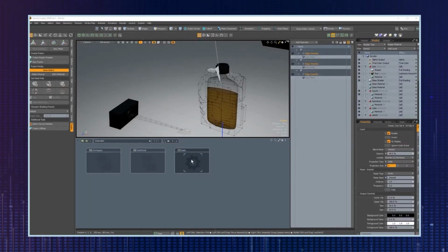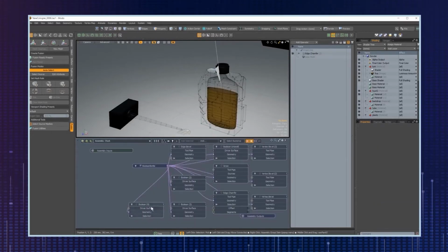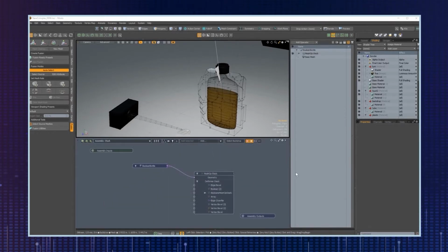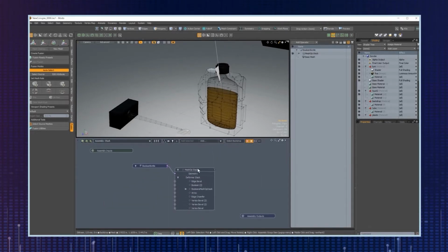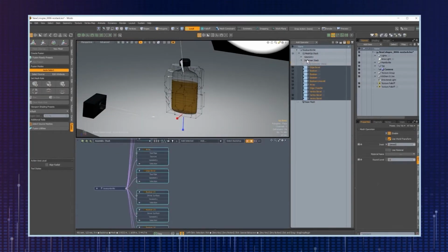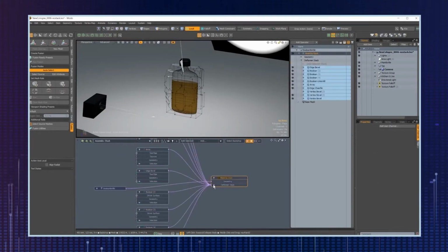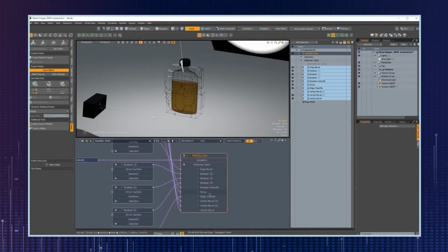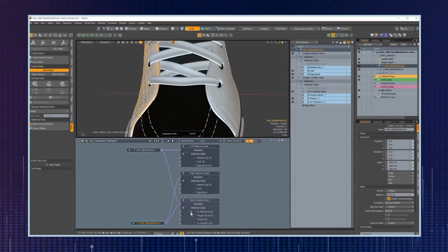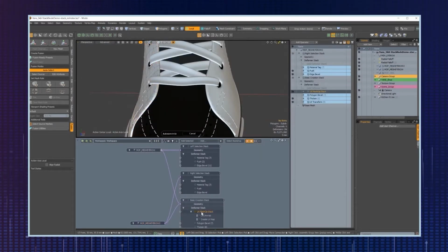It will help you manage your node graph links. For example, instead of having multiple links exposed from a mesh item in an assembly, you can use the MeshOps stack node to reduce this amount to one link. That's much better. The MeshOps stack node helps you streamline your node graph too, by enabling you to apply an order of operations to multiple items quickly and easily, and reorder them at will. You can nestle MeshOps stacks inside larger stacks for more precise control.